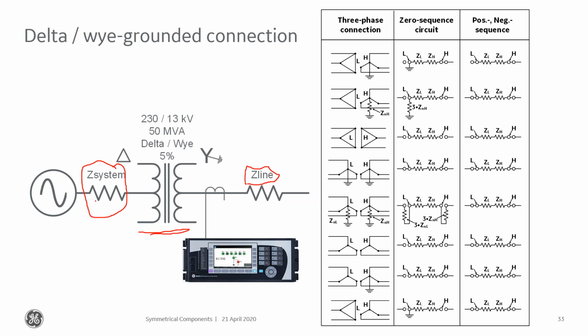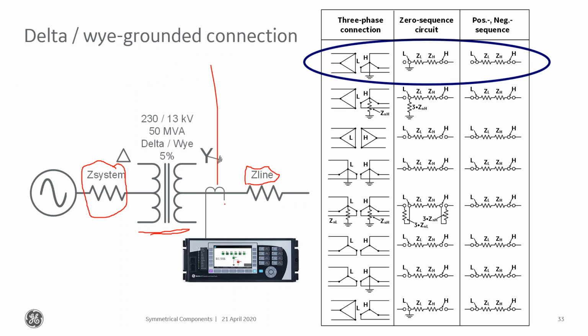If we look at this scenario here, and we look at what that transformer looks like to us, very important is, where's the meter location? That's the CT that I can calculate zero sequence quantities from, and that's where I want to do that. It looks like this side of the transformer is grounded, right? So my metering location is going to be right here and right here.